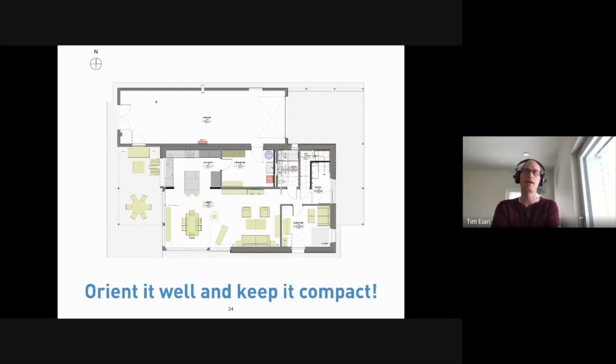A lot of people accuse Passivhaus people of oversimplifying structures. They're all boxes. I think in part what you're seeing there is also, since that's a more contemporary way to design, you see probably more modern people gravitating towards it. And that's just a form factor that modern architecture uses. So at any rate, the simpler you can keep the building, the fewer intersections, weird innies, outies, up, over you have, the easier it gets. And a compact building envelope with a better surface to volume ratio is going to be a more efficient building.